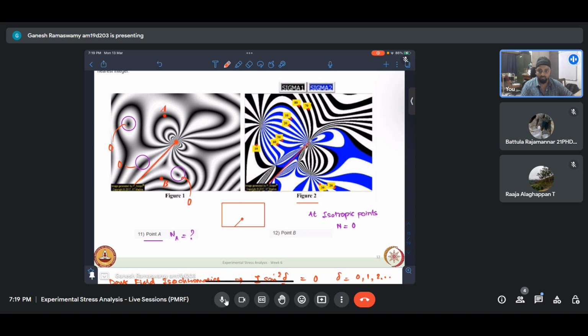Now we are moving towards the crack tip, and we are able to see that our fringes are getting denser, and our crack tip has very high stresses. So naturally my fringe gradient direction is this way, increasing that way. If this is 0, then what is this fringe order? This fringe that is coming is n equal to the next integer that I see in the gradient direction after identifying my 0th fringe order. So this is n equal to 1.